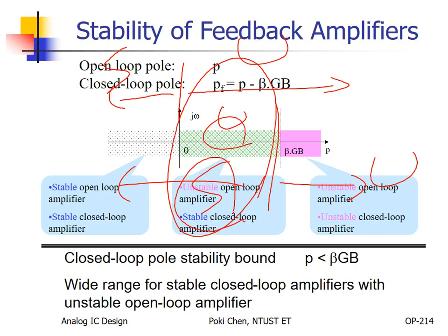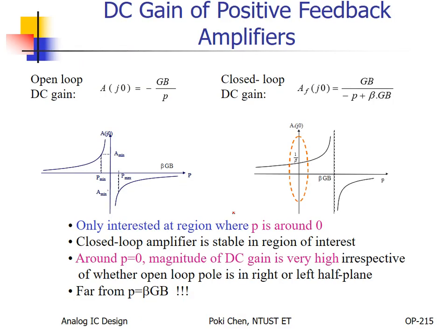Okay? Be brave. Yeah. Before I close it, there is something related to this. For such kind of positive feedback amplifier, positive feedback means the gain can be increased substantially. Okay, but all the other parameters of the open loop amplifier will be degraded. Who cares? Because we only need high enough gain.